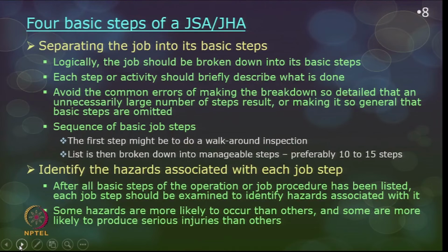Again a register is entered to record in which godown the reinforcement has arrived, and the characteristic features of that reinforcement are noted, and some samples may be taken for testing again if required. And then the empty truck returns back. So, like this there may be a series of steps. You may have to separate the job, identify one operation, loading and unloading of reinforcement. You will have to break down the job into a number of basic steps. Logically, a job should be broken down into basic steps. Only if you break down the steps will you know where the hazardous steps lie.